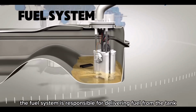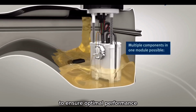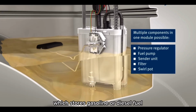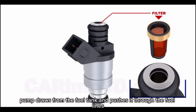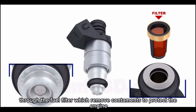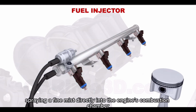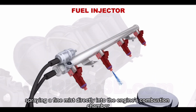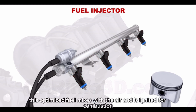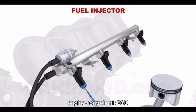The fuel system is responsible for delivering fuel from the tank to the engine precisely and efficiently to ensure optimal performance. It begins with the fuel tank, which stores gasoline or diesel. The fuel pump draws from the fuel tank and pushes it through the fuel lines to the fuel filter, which removes contaminants to protect the engine. In modern vehicles, fuel injectors atomize the fuel, spraying a fine mist directly into the engine's combustion chamber. This atomized fuel mixes with the air and is ignited for combustion. The amount and timing of fuel delivery are controlled by the engine control unit, ECU.